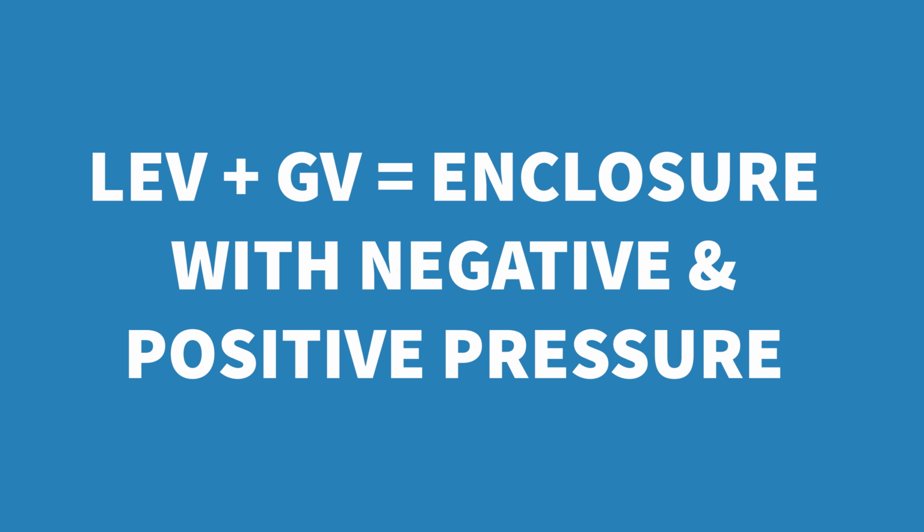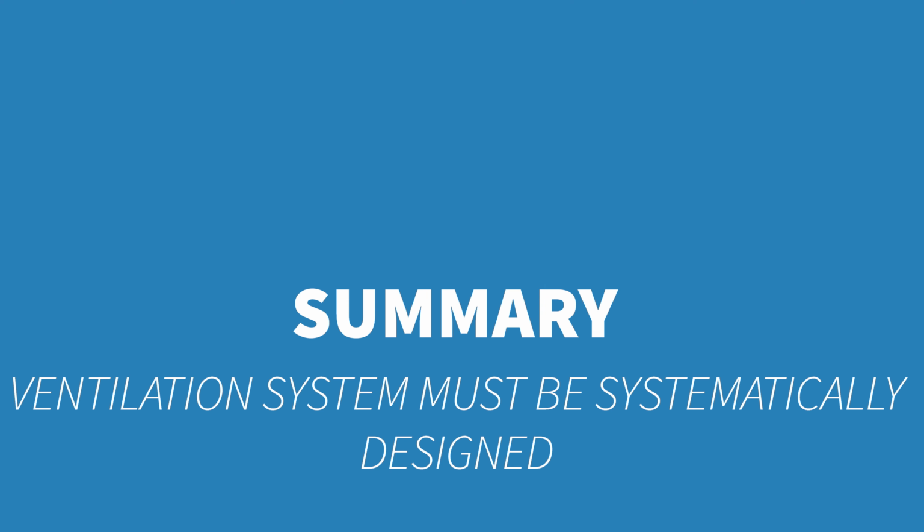Now, at this point, in short, we can summarize that the intention to install a ventilation system has to be systematically approached. It has to have an objective. First of all, it has to define the stresses. Then it has to quantify. This is always bypassed. We must quantify exactly the amount of that hazard. It can be empirically calculated or measured. Then, using this figure, we move on to defining the type of ventilation we're going to use.